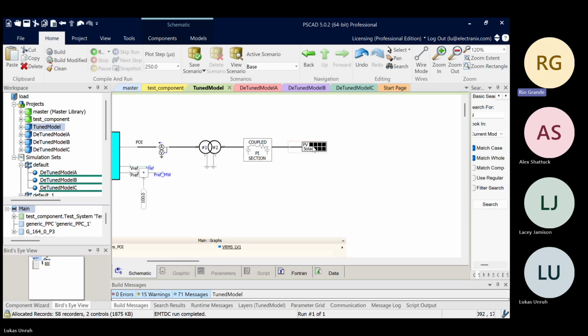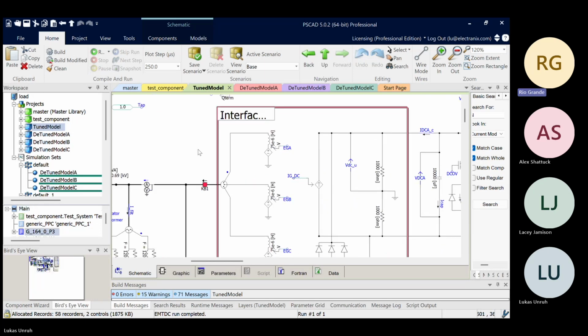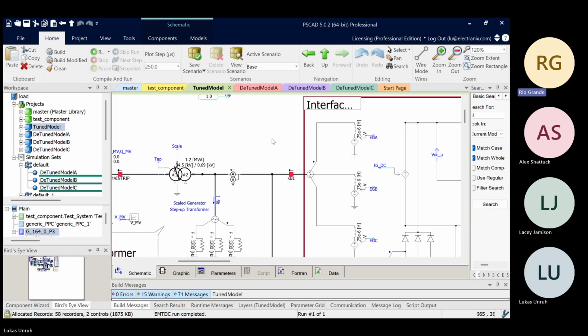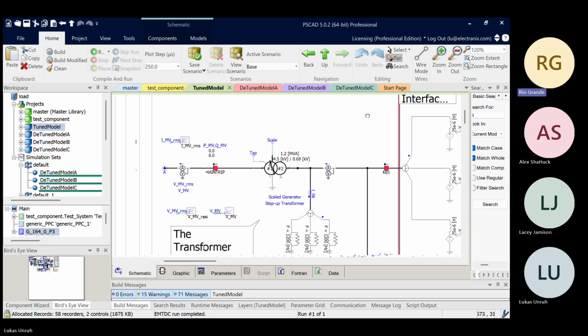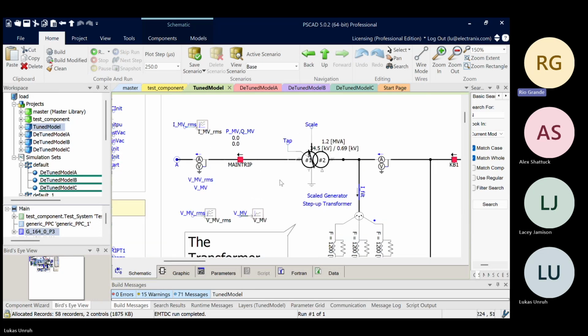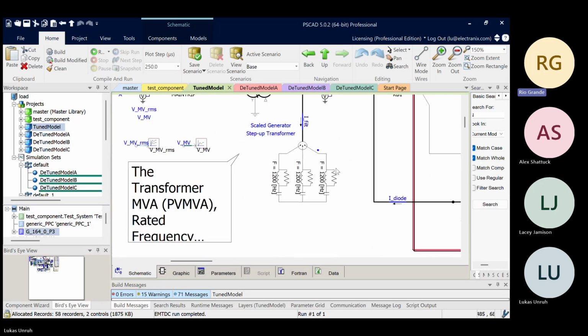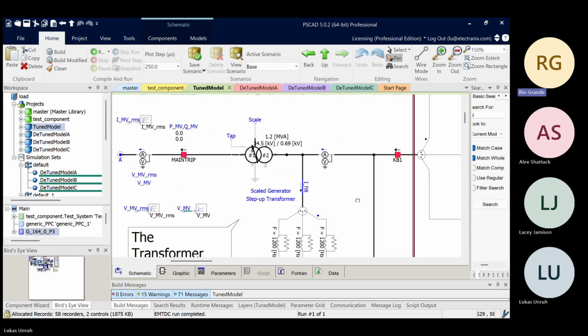And we can look inside of the PV inverter here. This is just a generic model. It doesn't represent any specific manufacturer or anything like that. But if we look at, going down from the main connection point here, we have a breaker, we have some metering, we have an inverter transformer with a scaling component on it, so we can represent various numbers of inverters. And we have some filtering that's happening here.